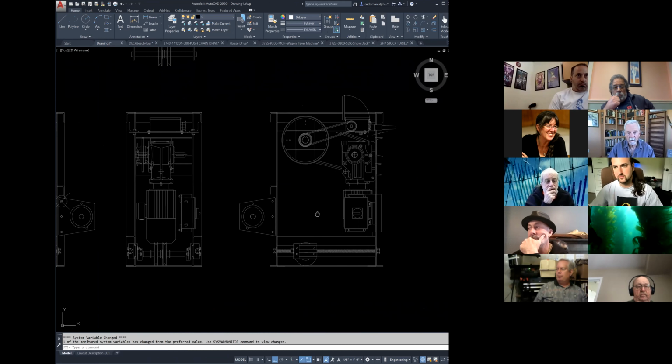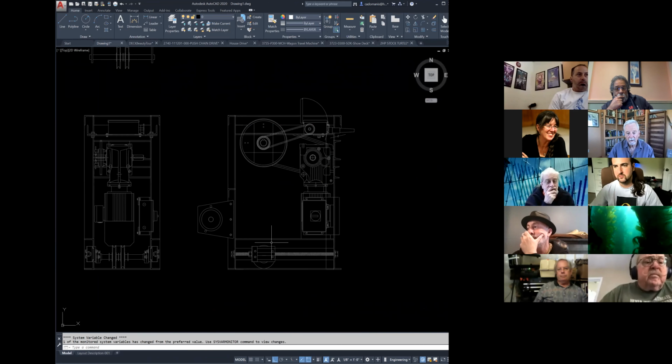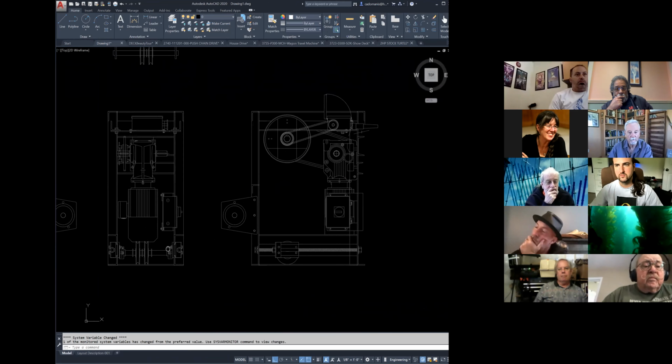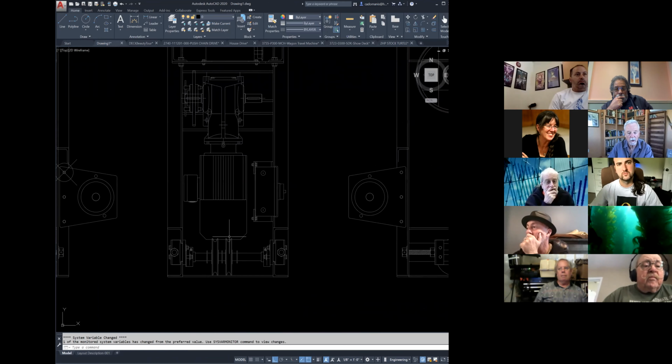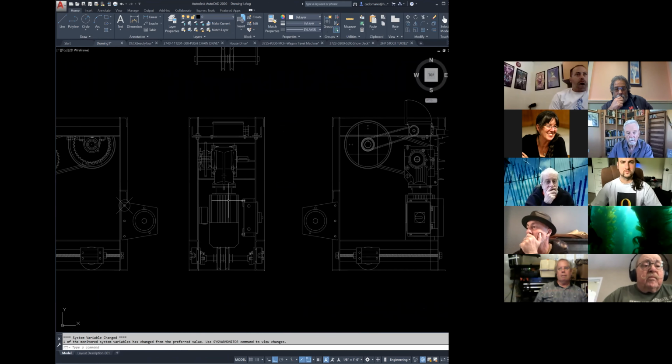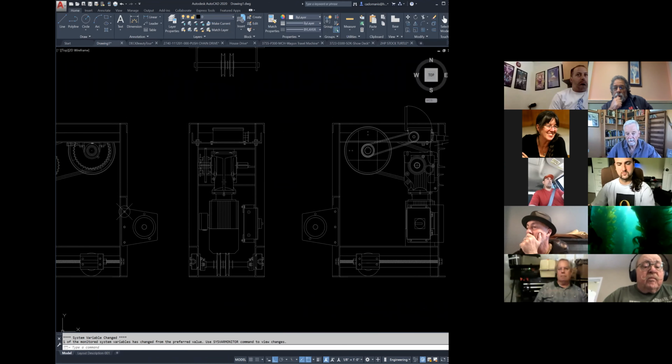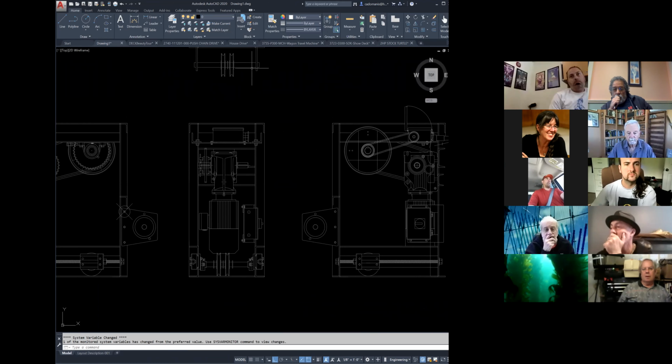There you go. Okay, so those sheaves will wander back and forth on that shaft, and they'll follow the cable on the drum as long as the distance between them and the drum is shorter than the distance from the pulley to whatever you're getting into in the track. And it works pretty well, but you do have to allow distance from the end of the track with these in order to account for the fact that the thing's moving back and forth 6, 8, 12 inches.